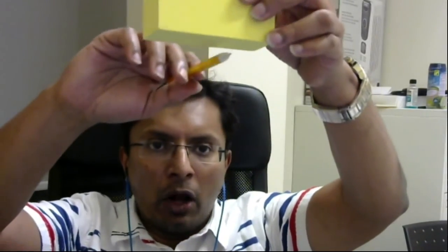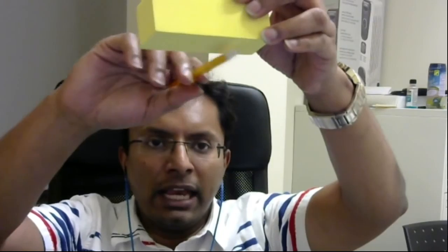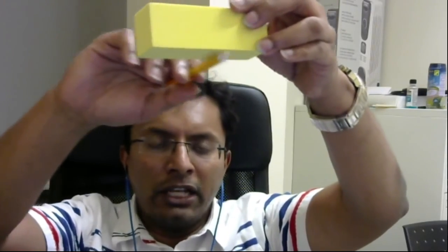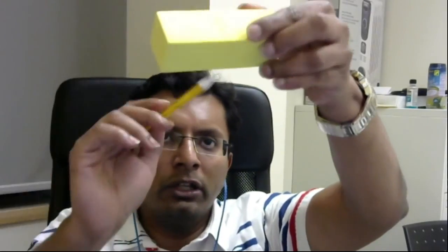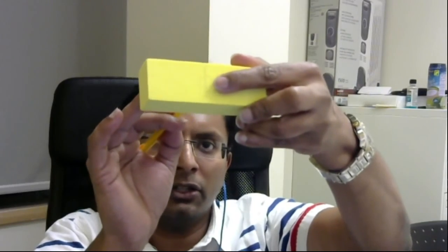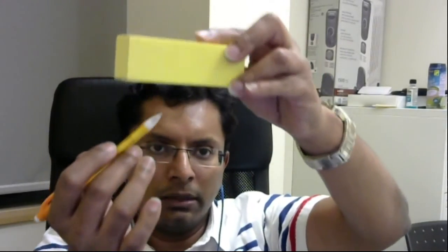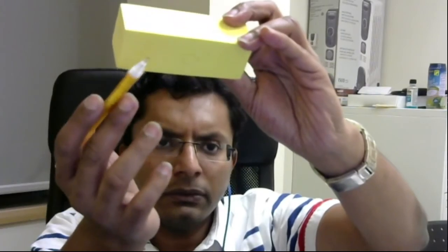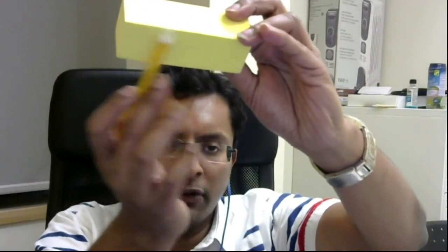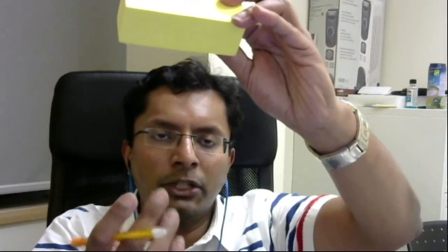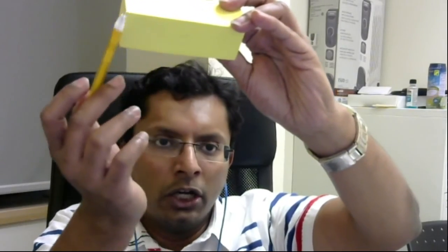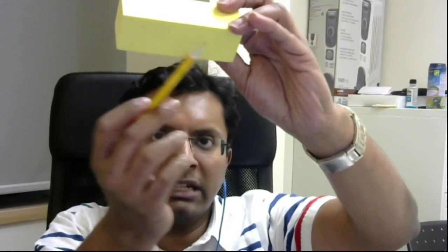For this surface, this is where my hole is. I'm always going to pick the face on which the hole would be made. If the hole is going through, I'll have the hole at the bottom surface here as well. I'm always going to choose the surface which is perpendicular to the axis of the hole to be my first reference. So that's going to be my reference A.